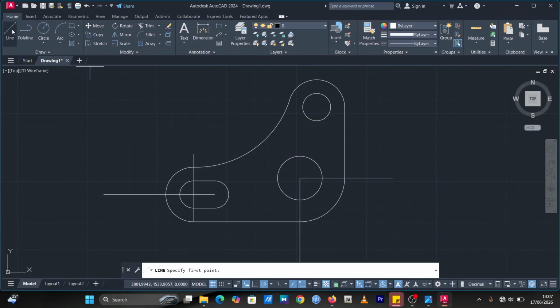So you pick your line tool and make sure this side, the by layer, is changed to center 2. So you can hover around to find your center, and you trace along it with a green line, and then click. Now you drag it down again, and then you click. So you are going to have something like this.